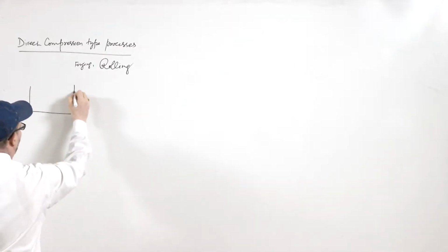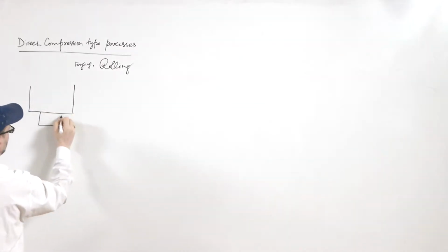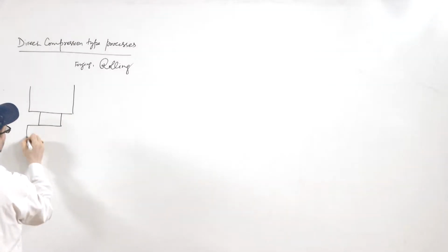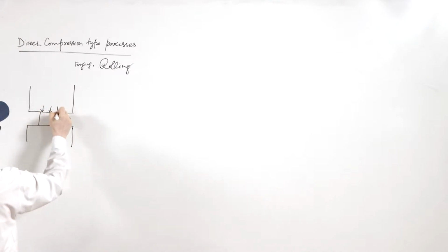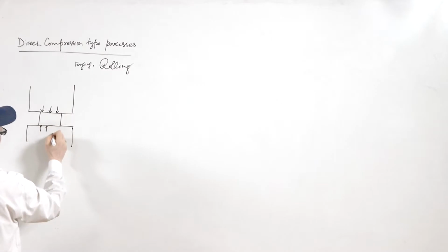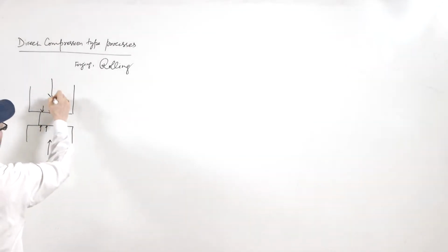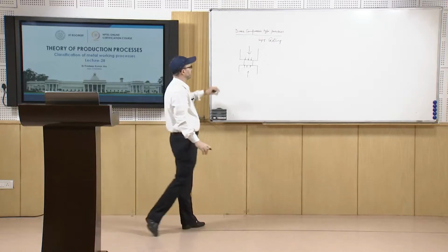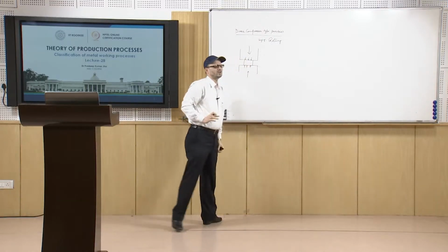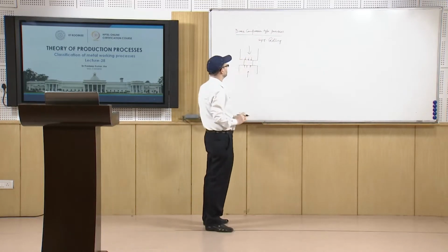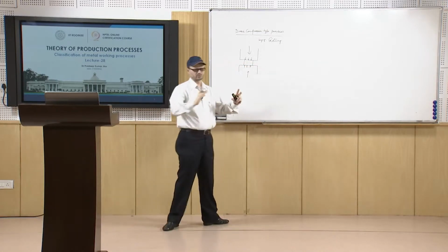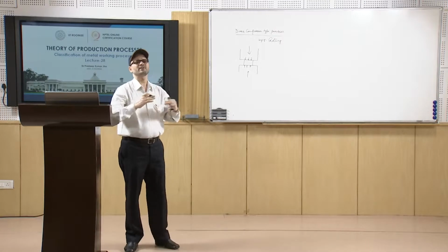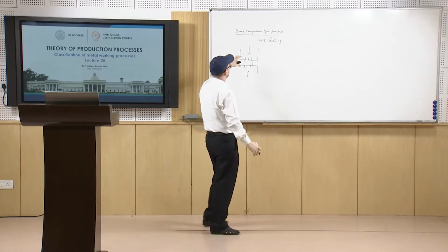Okay. So, in forging, you have a die and you have a workpiece. You have two dies and then you apply direct compression on this workpiece. Your forces are applied in this case, and the metal experiences compressive forces from both directions, and then it flows in this as well as in this direction.